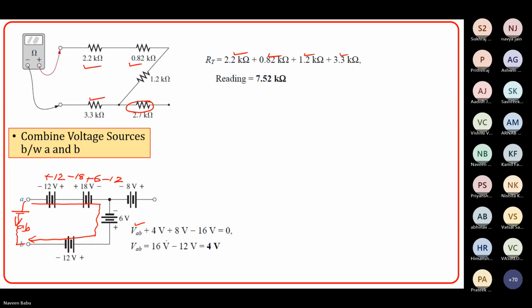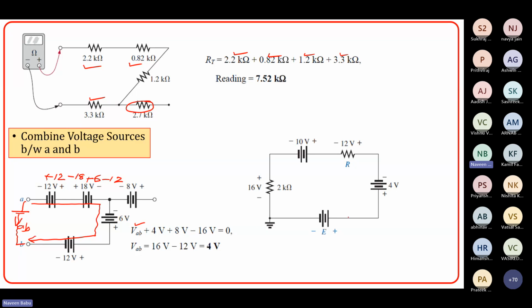Oh, okay, this pertains to, I think, some other problem. Yeah, to this particular problem actually. Okay, so it's slightly reorganized. So this voltage equation corresponds to this particular circuit. So VAB plus 12 volts minus 18 plus 6 minus 12 is 0. So therefore, VAB is 12 volts.